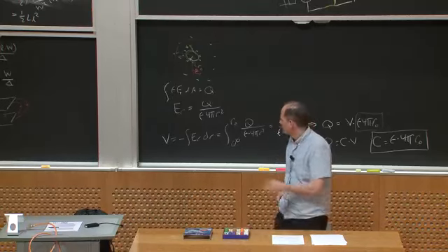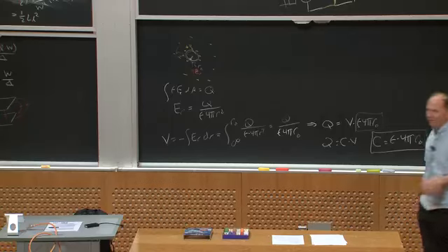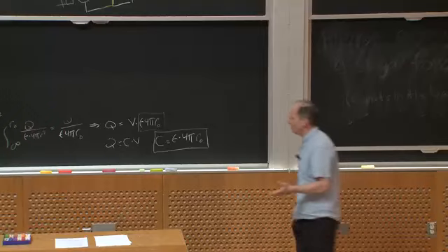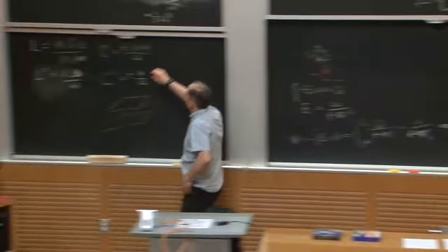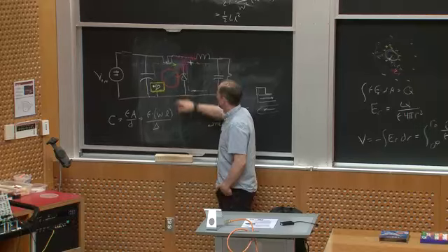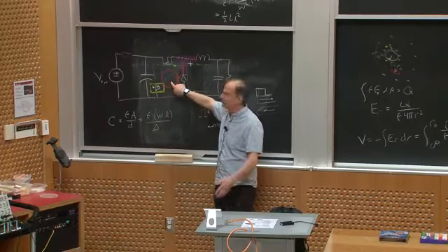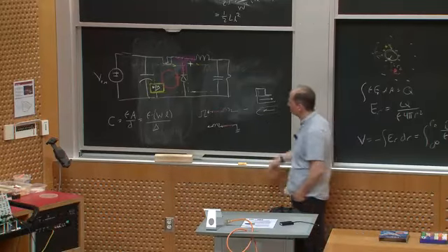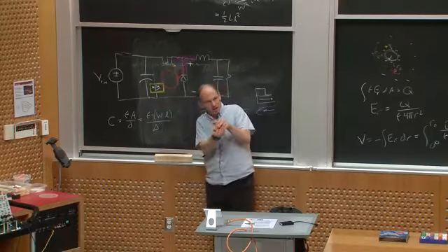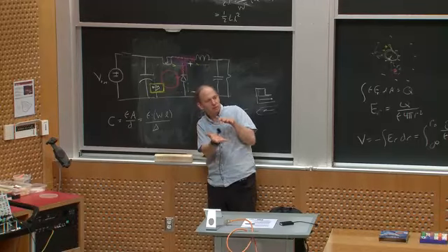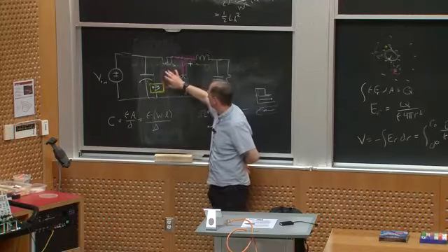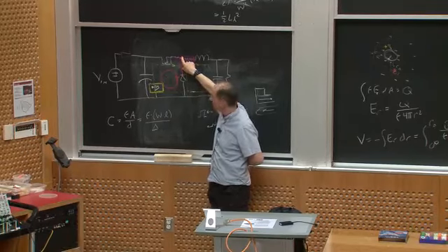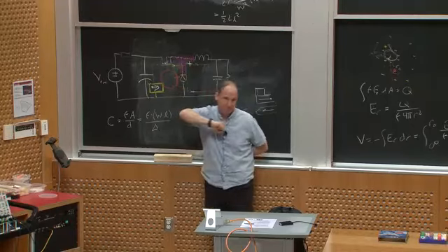So this is just sort of a case where Physics 101 leads you to some conclusions about how you should lay your circuits out, which comes back to make your loops very tight. And I could have done the same analysis for finding inductances of loops and so forth, right? You make your loop tight, you spread the area, you spread the current out to get the inductance low, and make the loop very tight. Don't use excess loop. Don't use excess trace area, especially at this loop and this node. Okay?